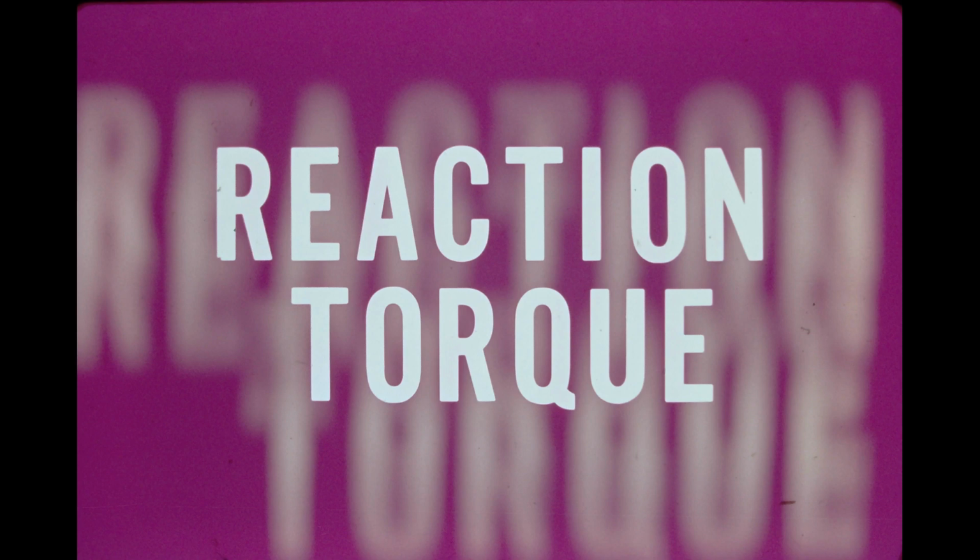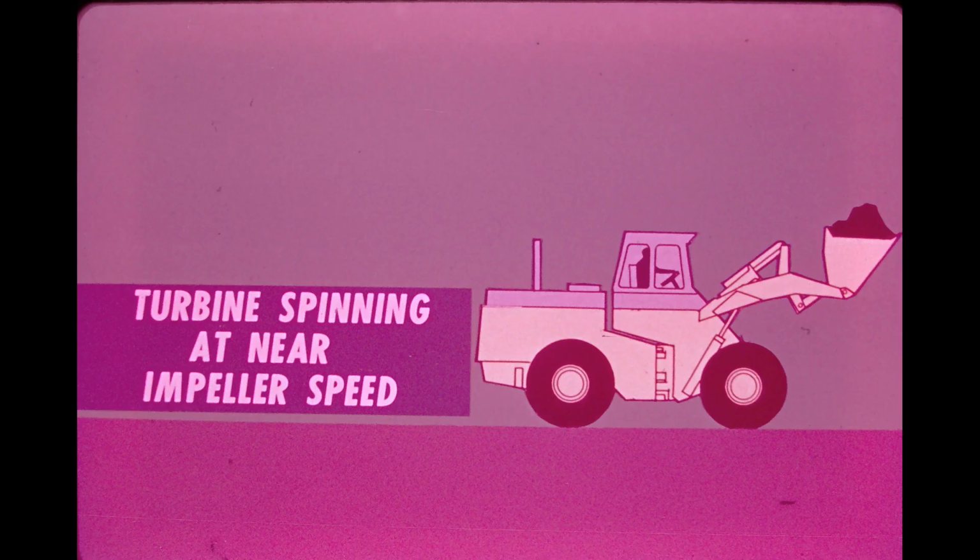Reaction torque, then, is the key to torque converter operation. It is the addition of reaction torque to the torque resulting from the impeller that allows the converter to develop more torque than the engine alone can deliver. Let's summarize what we're saying here with an example. If a payloader with a full bucket were traveling at full throttle on a good haul road, the torque developed by the engine alone and transmitted through the converter would be sufficient to move the machine efficiently. In this situation, the turbine would be spinning at near impeller speed, and there would be no vortex flow.